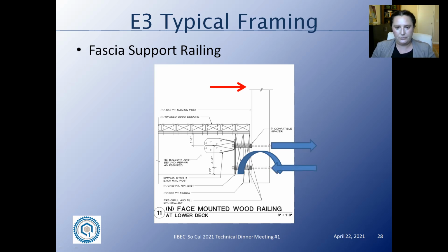So when you're considering where the structural concern would be on this balcony, you really want to look at these anchor supports here and the wood framing members that are connected to these supports. If any of these wood framing members or any of these anchor systems have some kind of decay and deterioration, that should be noted as a concern that needs to be addressed at some point.